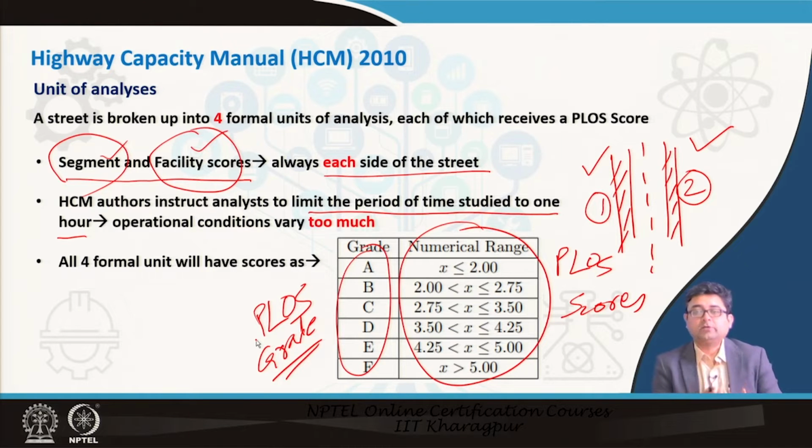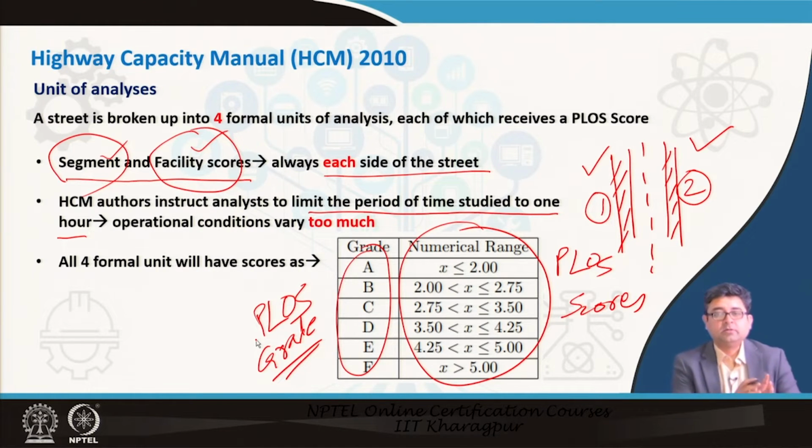Remember, level of service or pedestrian level of service is a performance measure which allows you to gauge how well your facility is performing as per the stated objectives or functions. If the function of the facility is to provide mobility to pedestrians, then how well is it providing mobility? Or if the function is to provide safe crossing of pedestrians, how well is the pedestrian crossing providing it? So, that is what any level of service, in this case pedestrian level of service, measures.